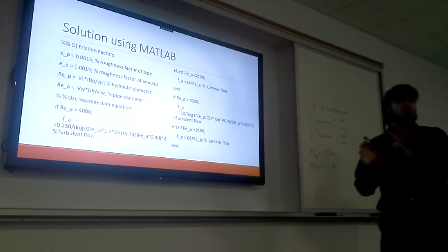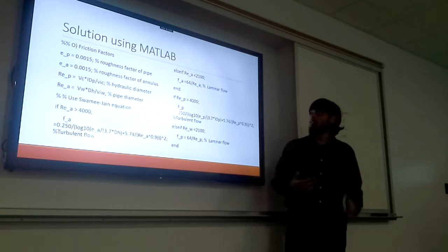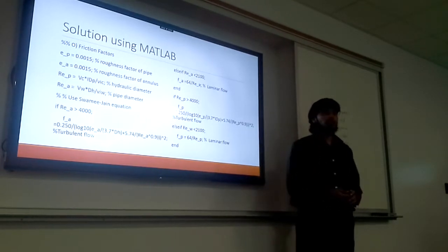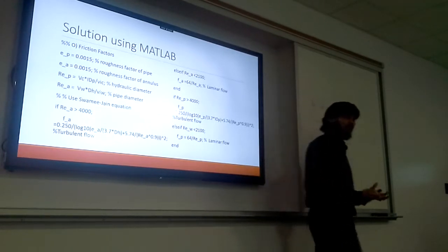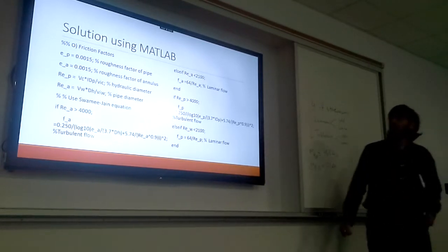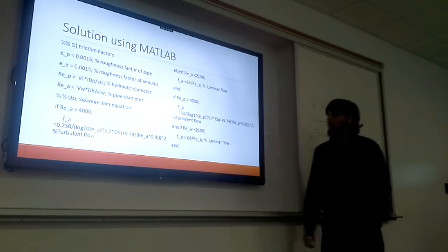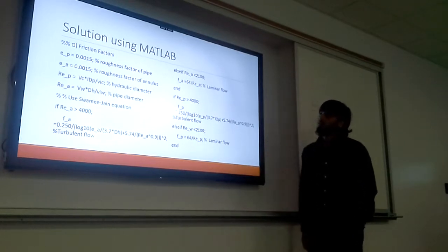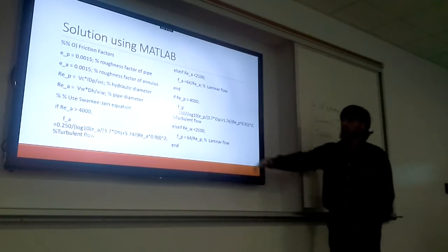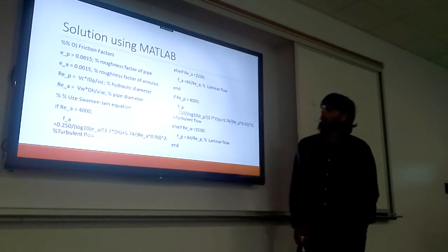Now let's go back to the mechanical balance, okay? The mechanical energy balance. In this case, it's the friction factors that get involved, right? The flow through the pipe, the pressure drop, that's where the mechanical energy balance comes into play. So we talked about heat balance, now let's talk about the mechanical energy balance. And in this case, we have to talk about friction, which then obviously involves viscosity, which you'll see when you apply the Reynolds number.